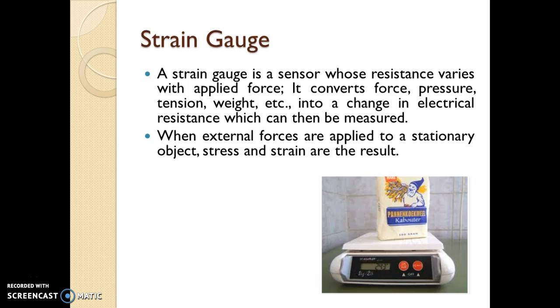So strain gauge is a sensor whose resistance varies with applied force. We all know that force, pressure, tension, weight, they all are related. They can be converted from one form to other form, and therefore we can use strain gauge to measure force, pressure, tension, weight, etc.